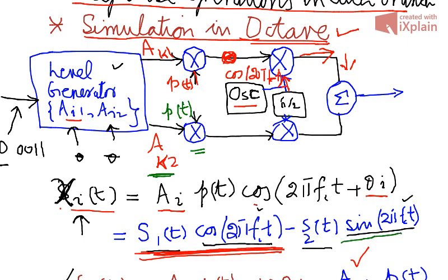We need minus sine of T. This pi by 2 shifter is available in the diagram, which shifts the oscillator output by pi by 2 radians, and we get minus sine 2 pi f ct here. This will be multiplied with the signal coming from this branch, which is the product. Now if you observe your signal at this point, you get this signal.